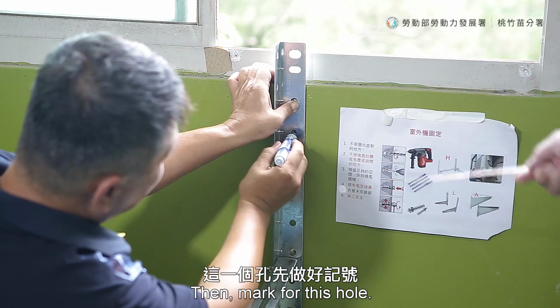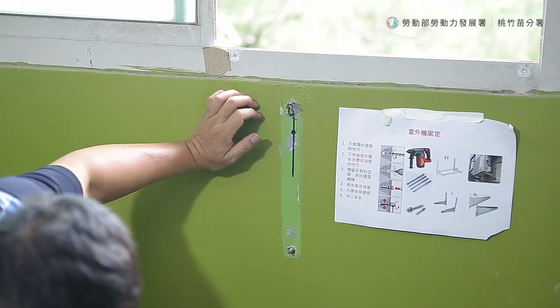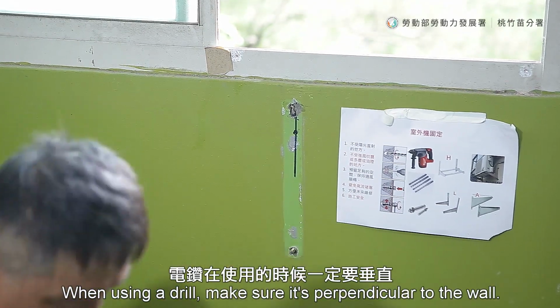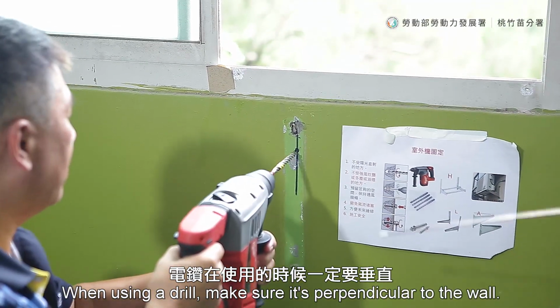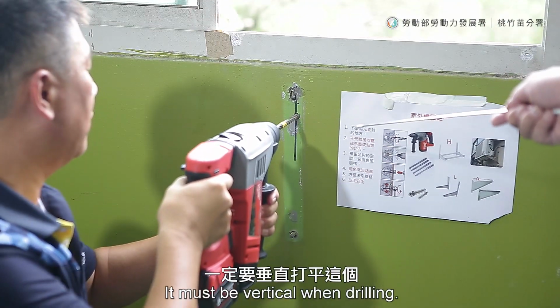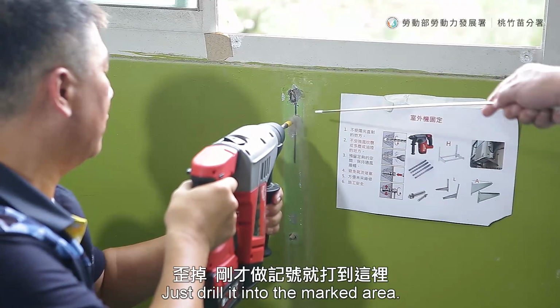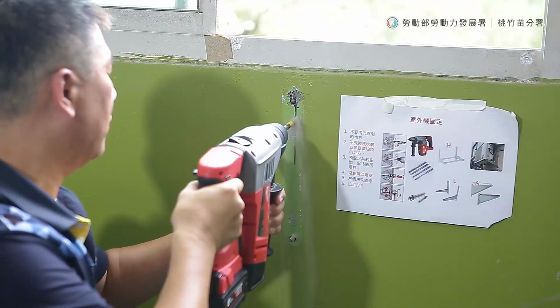Then mark for this hole. When using a drill, make sure it's perpendicular to the wall. Don't apply too much force. It must be vertical when drilling, so that the expansion bolt can go in straight. Just drill it into the marked area.